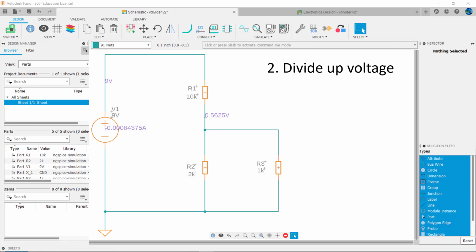If you want to make sure the voltage doesn't drop significantly, make sure the resistance you add across the resistance is much higher. At least 10 times is a general rule of thumb. For example, 22K, or better still, 220K.